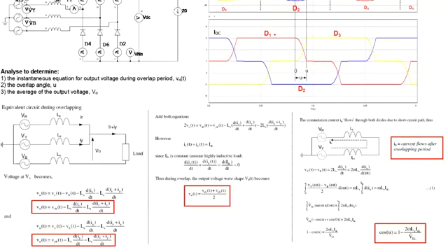If you consider D1 and D3, the current that will flow after the overlapping period is actually through the yellow phase. So you must follow the yellow current direction, not the red current. If you follow the red phase current, you will be clockwise. But because after the overlapping period the yellow current will flow through the circuit, we have iu set to follow that direction. Having that equivalent circuit, you then solve for KVL around the loop.